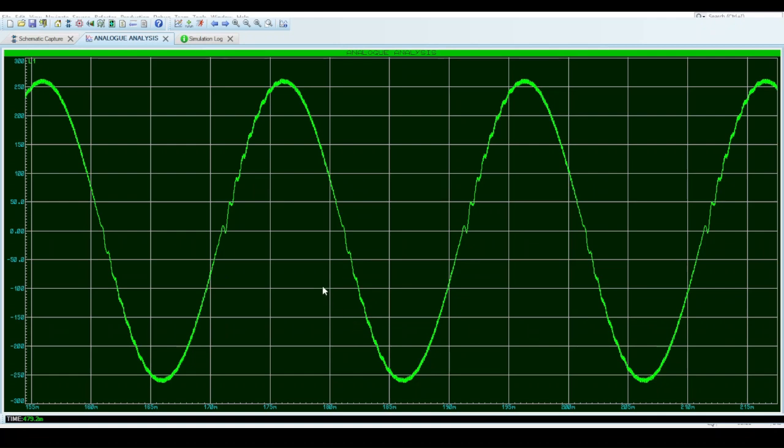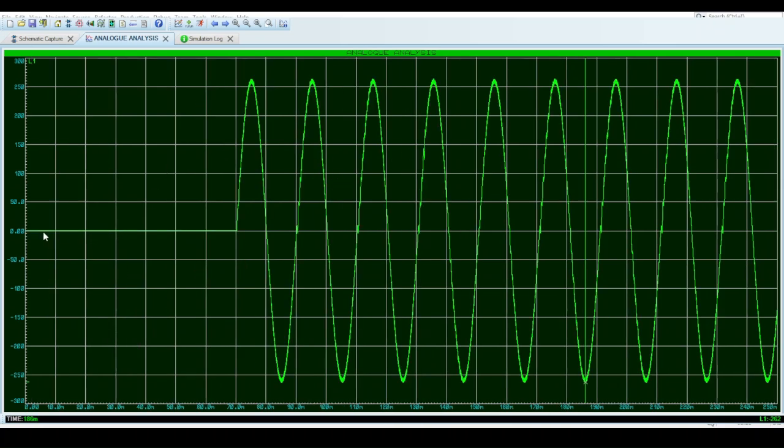Basically that can be attributed to the fact that the resolution is not that high. So essentially we're doing 50 changes for every 10 milliseconds, and well, 100 duty cycle changes for every 20 milliseconds, which is not excellent. So we look at that, so it's basically 262 volts peak to peak. All right, and obviously this time region there is basically the time it takes the microcontroller to calculate. So it takes about 70 milliseconds to calculate all the values for the array and just to populate them.